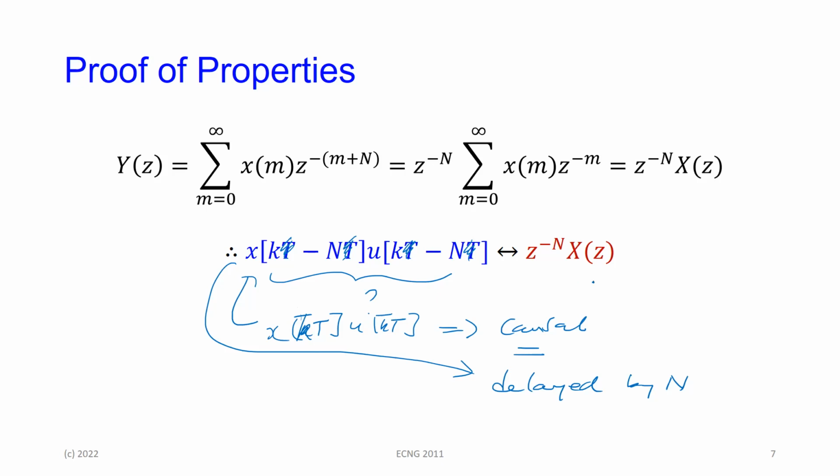And the Z transform of that is the original Z transform, but because you delay the whole causal set by n, you have to multiply this by z to the minus n. This is the equivalent of the Laplace transform version, where if you have y giving you Y(s), then dy/dt will give you sY(s). All right?